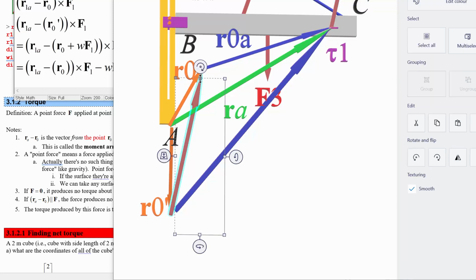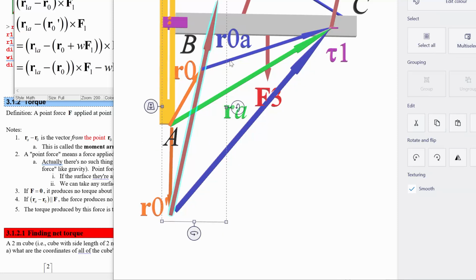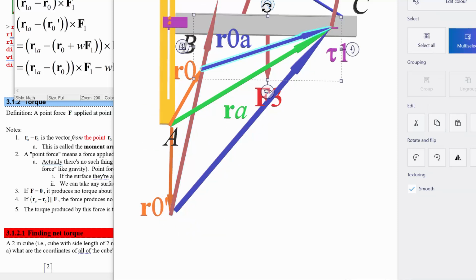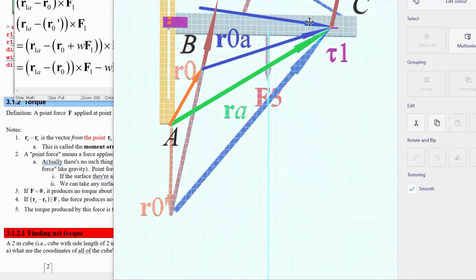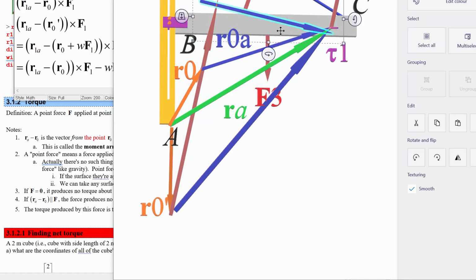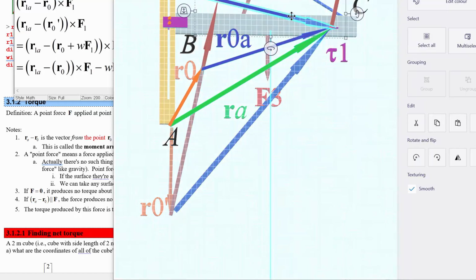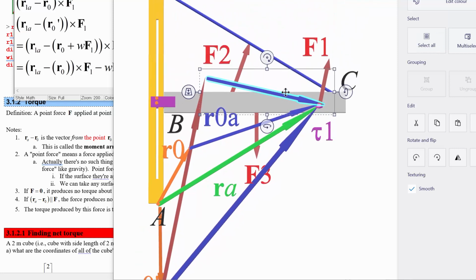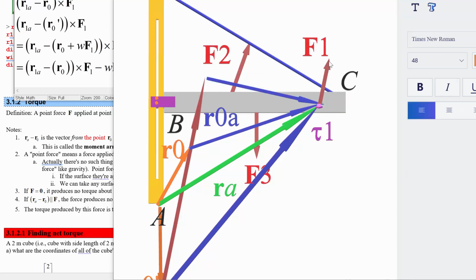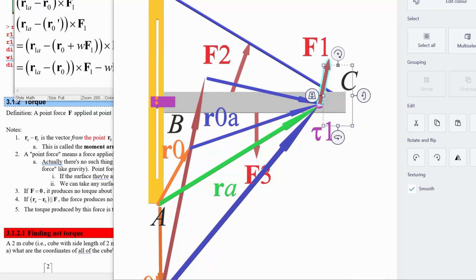So the distance away perpendicular, meaning that we could imagine extending this and then forming a new vector, the smaller one that just shows you the part that's perpendicular to that original F1 vector, and using this to find the torque instead. The advantage is that because these are all perpendicular, we don't have to deal with that sign when we're calculating it, and it shows us more directly what the torque is that's created by this vector.